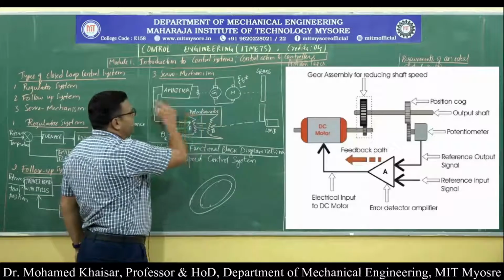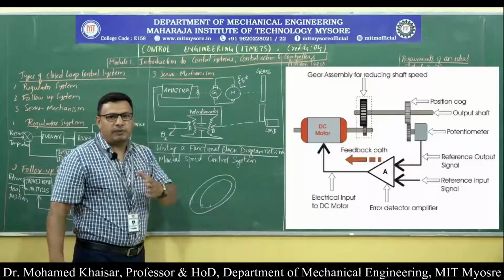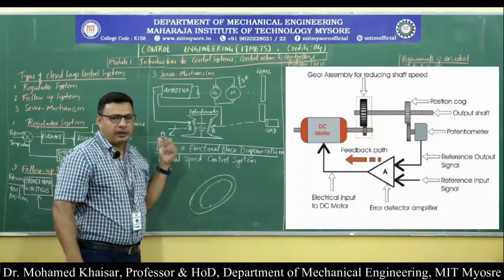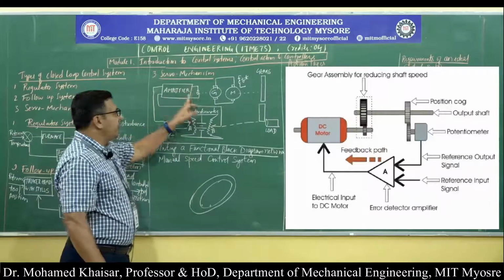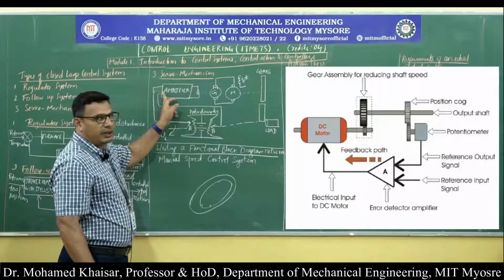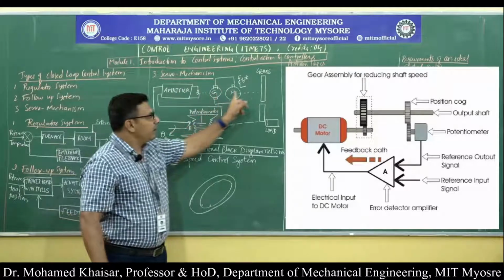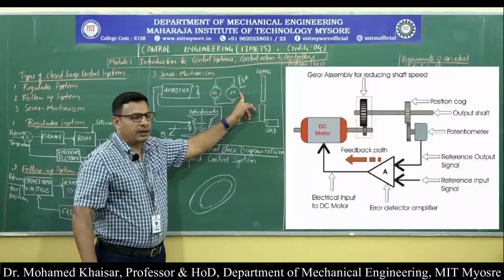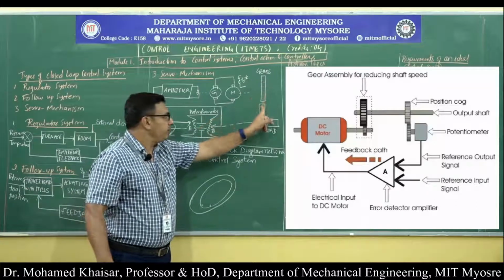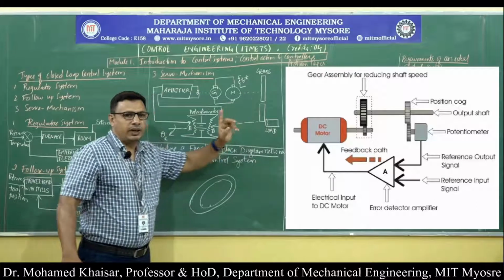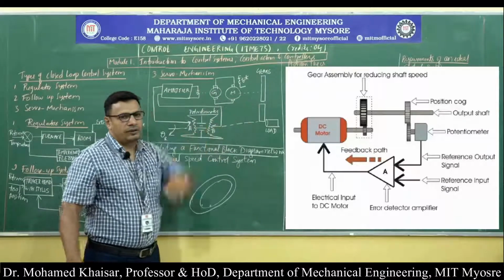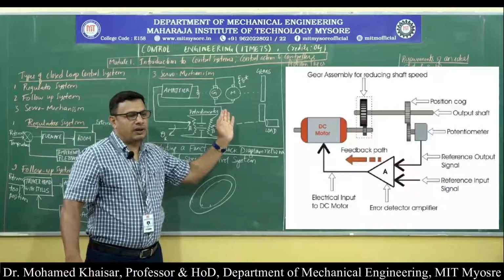This is fed to the amplifier, and the difference between what we wanted and what is actually available, the error voltage, is amplified and given to the generator unit, and again the motor is going to rotate by some angle, and the gear meshed with the output gear is going to rotate, and that gives us the output. That is what is called the control.